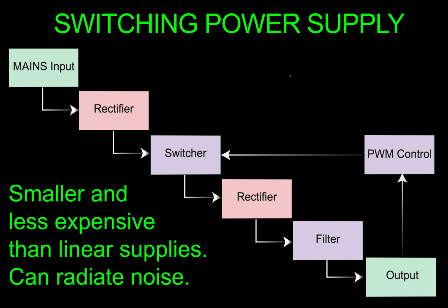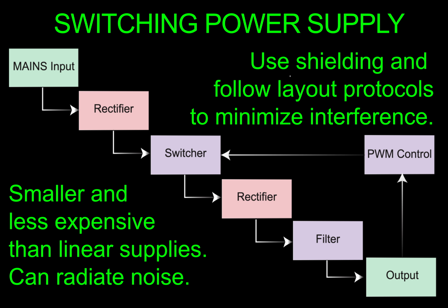Because switching power supplies operate at higher frequencies, they can radiate noise and interfere with other circuits. Interference suppression measures, such as shielding and following layout protocols, must be taken.